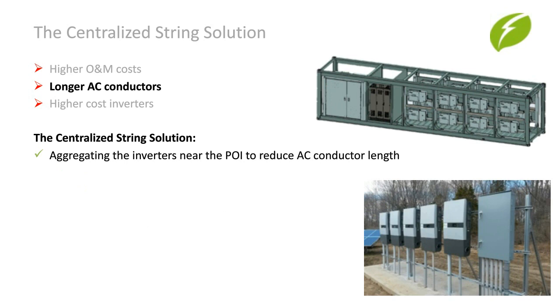Solving the longer AC conductors is easy. Centralized string means that we are installing the inverters in a group or on a skid close to the point of interconnection. Just like longer AC runs were inherent to distributed string systems, short AC runs are inherent to centralized systems.